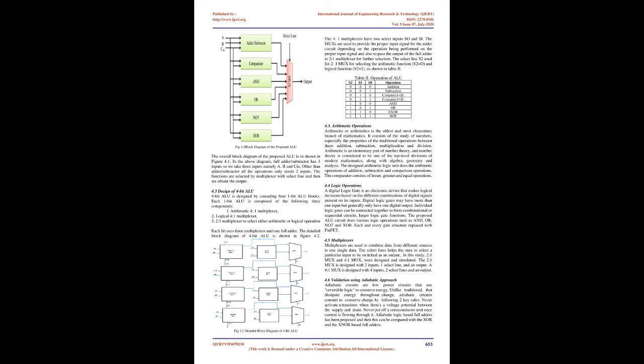The effective width of a FinFET is 2NHfin, where N is the number of fins and Hfin is the fin height. Multiple fins lead to a high on-current transistor. FinFET width is quantized in terms of number of fins. Some key design factors like performance, power, and functionality per on-current ratio are also dealt with.